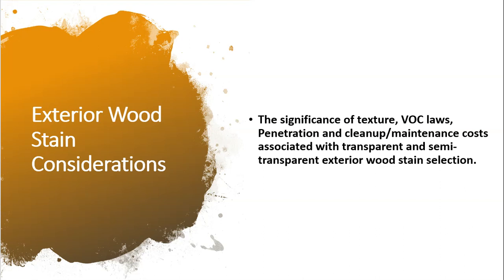The significance of texture, VOC laws, penetration and cleanup, and especially maintenance costs associated with semi-transparent and transparent wood stain selection became an important webinar when, on my basics webinar for wood specification, the architects asked me to expand on the stain use.